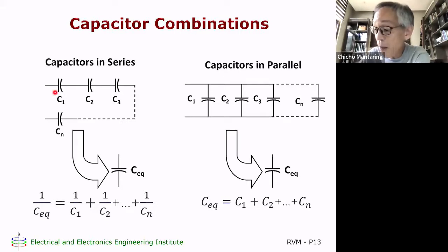Okay, this is all the same I, and so you add the individual voltages, which are actually integrals. So you have 1 over C1, the integral of I dt, 1 over C2, the integral of I dt, and dun lumalabas yung 1 over C equivalent is 1 over C1 plus 1 over C2 and the like.